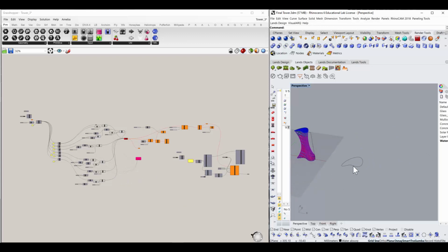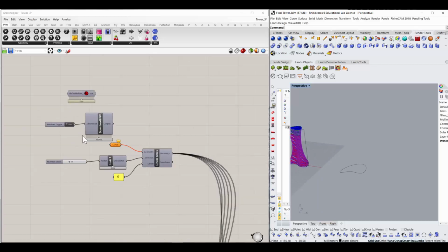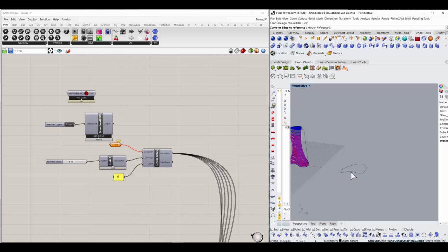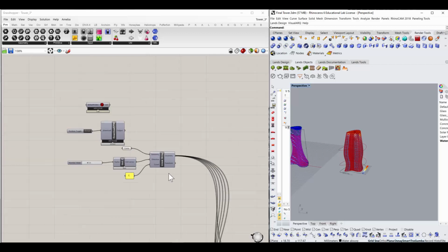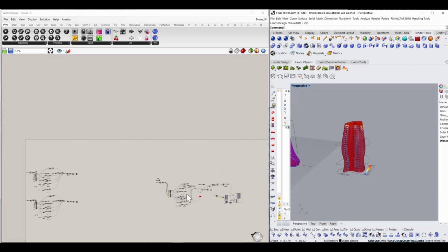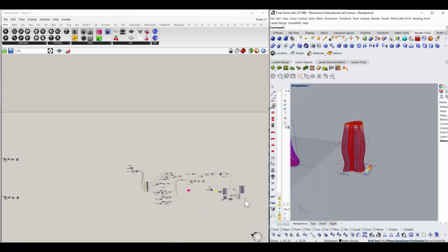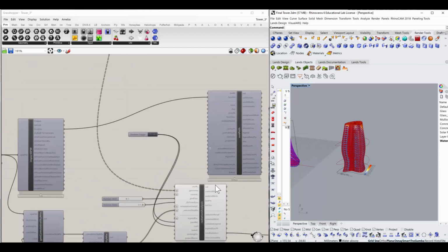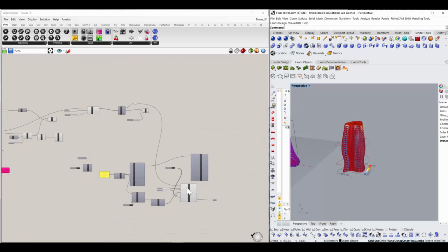After manipulating this curve, I have to select this curve and put it into this function. So you can see it already created an envelope surface, and it also did Ladybug analysis for this entire surface automatically because the Ladybug plugins are connected.